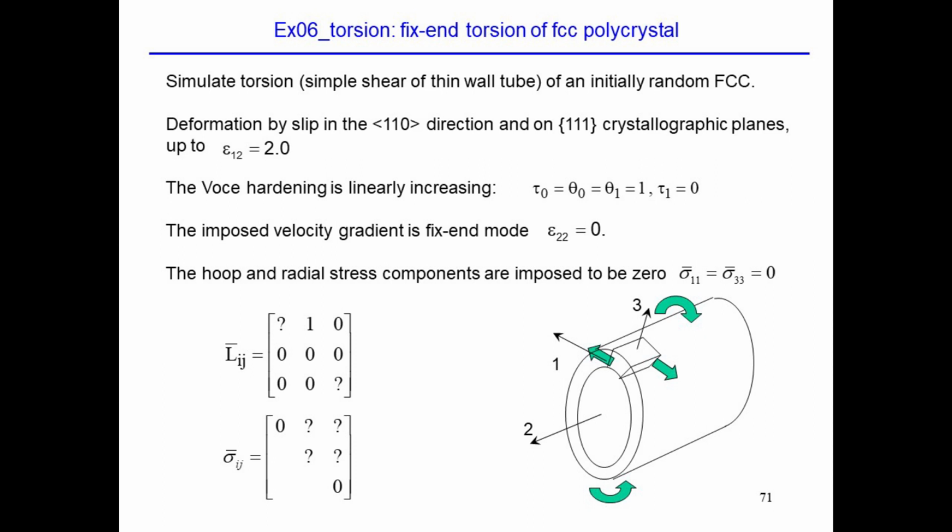Those two things can happen, and they do happen. Then you impose the shear 1,2, you put a force on this plane that is pointing in direction 1, on this plane that is pointing in direction 2, L1,2. And then the other two shears have to be 0, because it can be demonstrated that the plane of deformation has to remain planar, that it cannot start moving around.